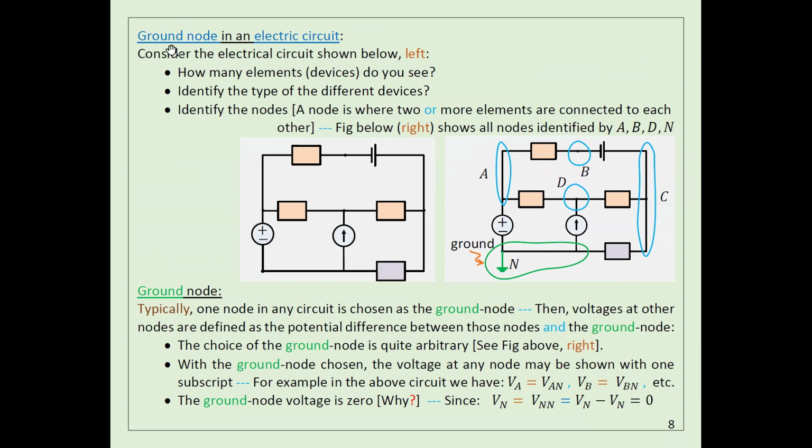And then you also need to know what I mean by ground node. Ground is one node. I'm going to consider the voltage of this one to be 0, okay? And actually, this would be my reference point. That means if I calculate the voltage here, and I say the voltage here is 7, I say this point has a voltage of 7. Usually, voltage means the difference between two points. Right? You got what I'm saying? That's true. So when I say the voltage here is 7, that means the voltage difference between this one and the reference here is 7. Okay.